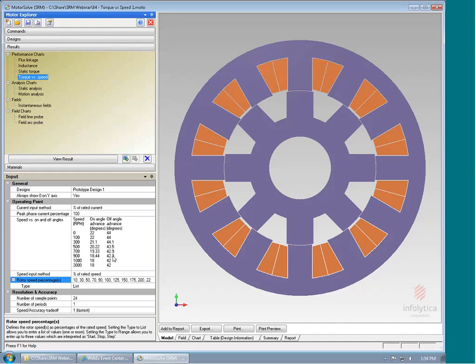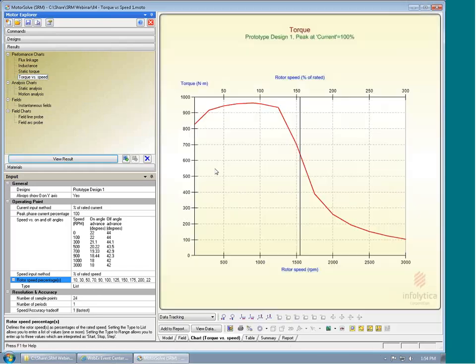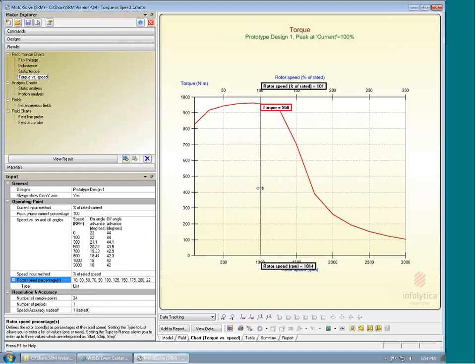But you can see here that we've actually imported and set up firing angles for each of the various speeds, and then we step through and have denoted and will show the torque speed curve for this machine from 0 to 3,000 RPM. And you can see here that over in the operating range, which is roughly with 1,000 RPM, we have just under 1,000 Newton meters, and a fairly broad range for that. And a little bit of a roll off after, say, 1,200 or so, 1,250 RPM.